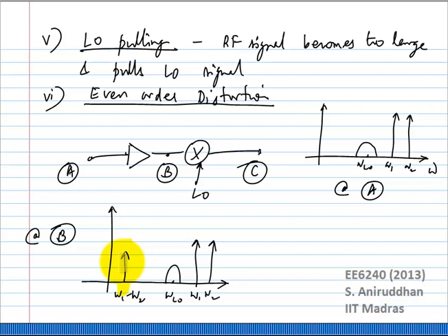So you take it up to 10 microvolts, right? And it goes through a mixer, and let's say the mixer also has a gain of 10, so that's 100 microvolts. The typical input referred DC offset of an amplifier may be in the several millivolts, if not tens of millivolts, right? So it is not a small problem. It is definitely not a small problem at all.